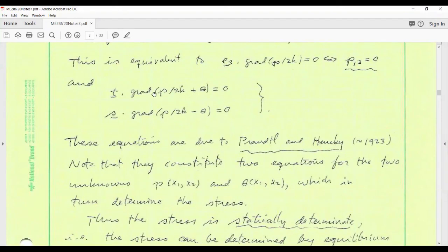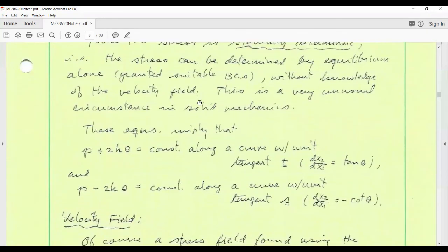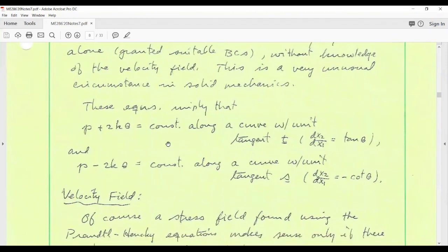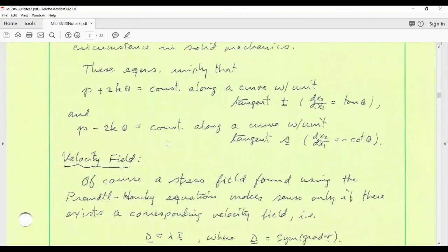The equilibrium equations that we've reduced to this form turn out to be of hyperbolic type. If you've encountered PDEs before, the equations of plane plastic flow are hyperbolic in character. Whereas the equations of elasticity, for example, are elliptic in character, elliptic type, a dramatically different kind of partial differential equation. And these so-called hyperbolic equations generate these so-called Riemann invariants that you do not find in elliptic systems, of which elasticity is a typical example. So you could be a wonderful elastician, a great elastician, and that wouldn't help you at all in solving problems of plane plastic flow, because the mathematical structure is so different. Vice versa, you could be really adept at solving these equations, and that experience would not help you at all in solving elasticity problems.